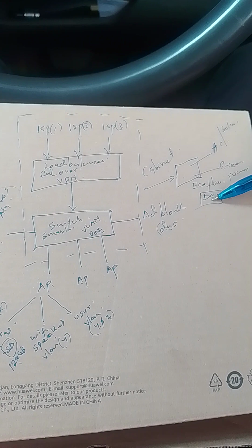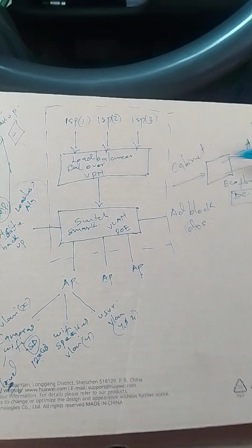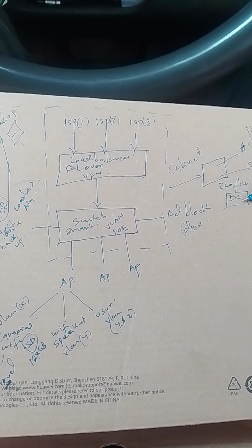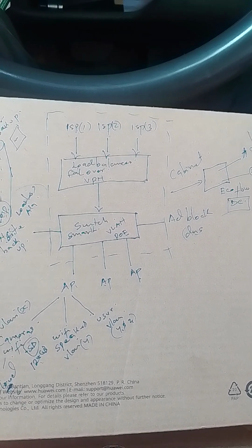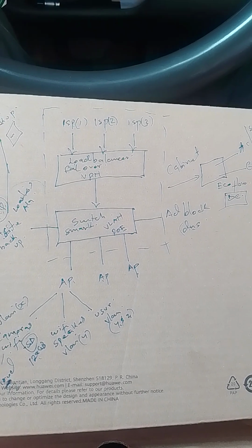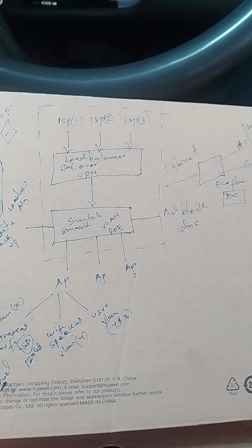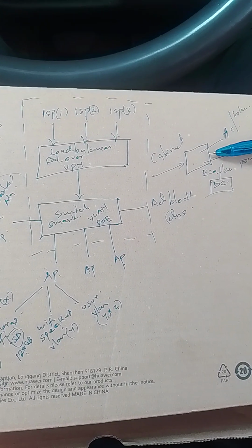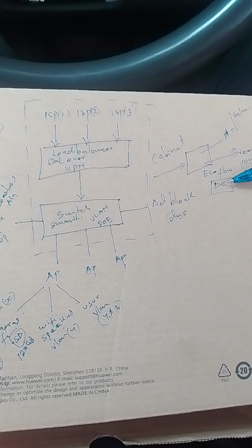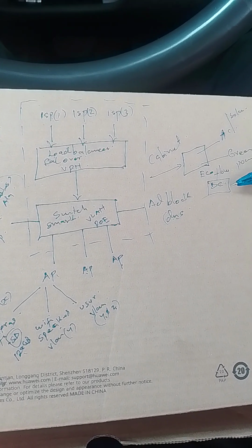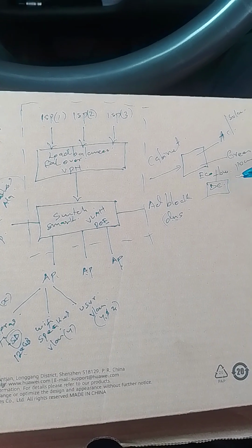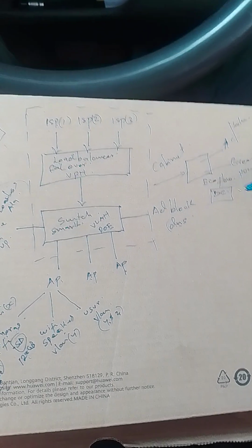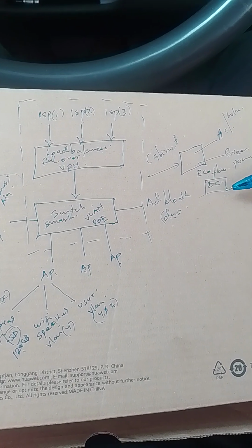So during daytime, when we have solar, this power will go straight to the cabinet. Some of it will be used to charge DC. So AC, the Kenya Power and all that will be a backup for us, because we'll be using solar entirely. In the evening, we're going to use AC power while charging our batteries. In the event it is in the night and we have a blackout everywhere, Kenya Power is not there, what we'll use at this point is the DC backup power.